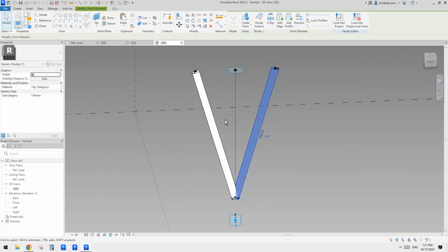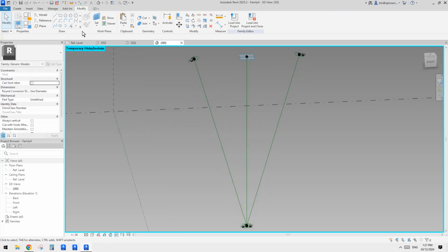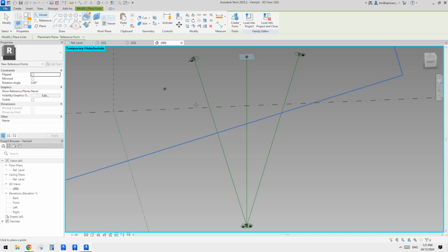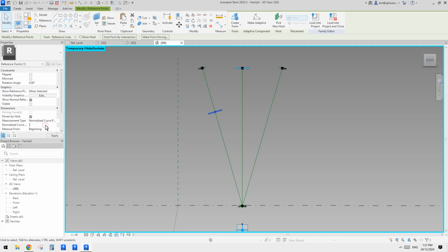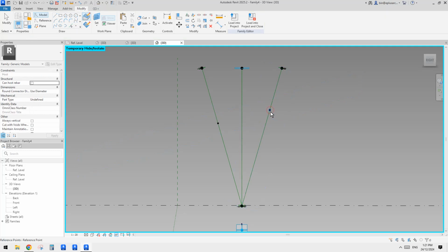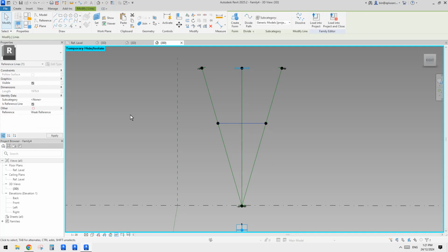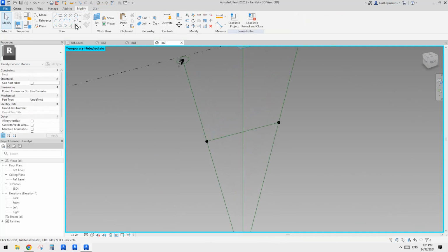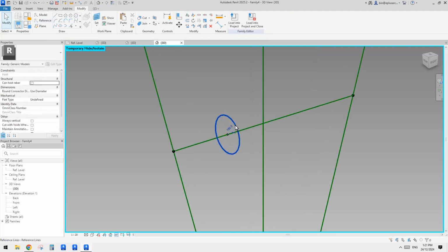So now, okay, we also need a horizontal member. So let's call it H. Place a point, use draw on face. So this time, let's just try to find maybe 0.6, 60%, and place another point on here. So we can use the same 0.6, so they will be at the same height. And then you can use a spline through points, make a reference line. And then we can place another point, draw on face. Place another circle, draw on work plane. So we create another one, right?